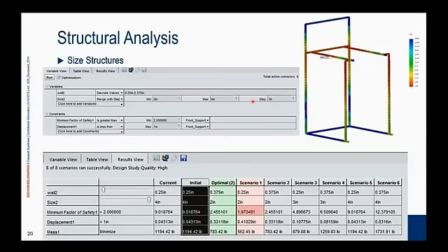inch and 0.375 inches. The requirements I've specified are I want a factor of safety greater than 2, and I don't want it to deflect more than 1 inch. And we could put additional constraints in there if we've got multiple studies. Could be vibration if you're really interested, or just other load conditions. We can put those requirements in there as well and get it to compare them.